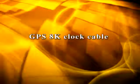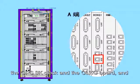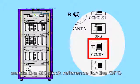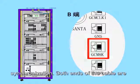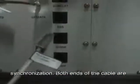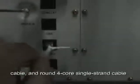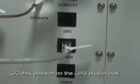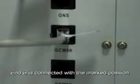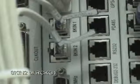GPS 8K clock cable. The GPS 8K clock reference cable connects the GPS 8K clock and the CLKG board and sends the 8K clock reference for the GPS module of the clock board for phase lock processing to implement system clock synchronization. Both ends of the cable are crimped shielded plugs for 8P8C straight cables. Round 4-core single-strand cables are adopted. End A is connected to the GCM 8K position on the GPS plug-in box. End B is connected with the marked position 8K in 2 of RCKG1.